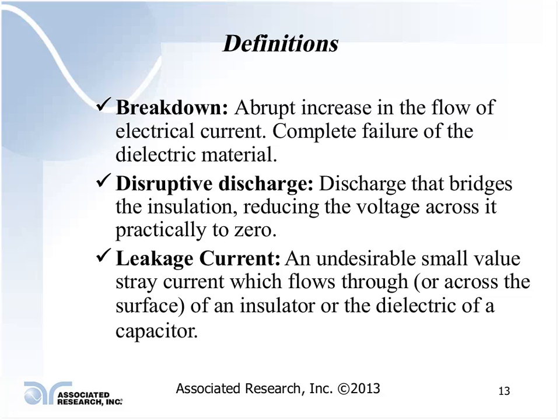You have some point of traceability that if you have to, you can retest a day's worth of production if by chance you find a problem, okay? So if you're doing your daily fail verification and it will detect a failure, then if you detect a problem, uh-oh, wait a minute, this thing should have failed whenever I did this.